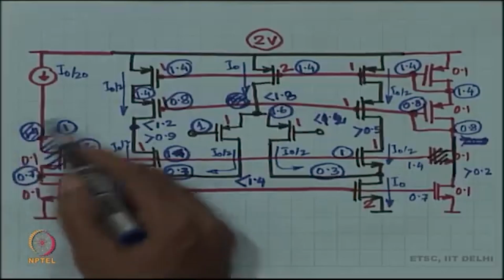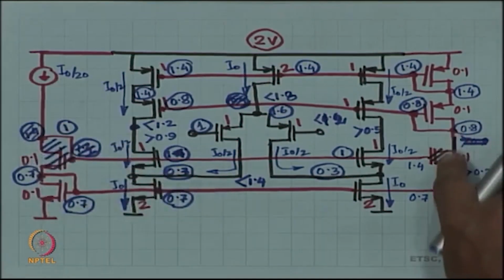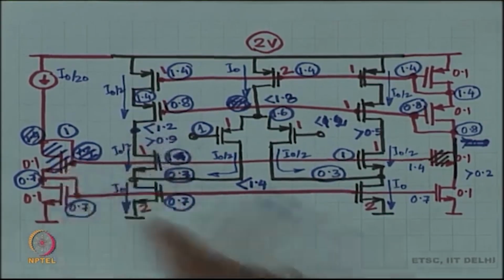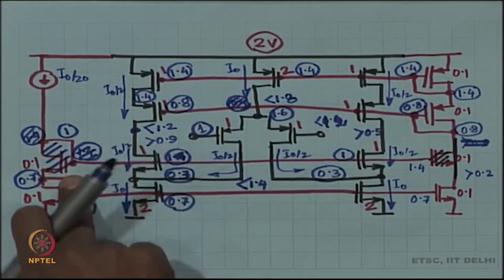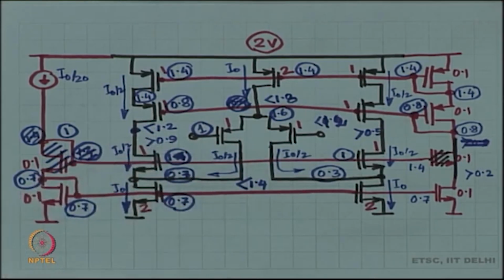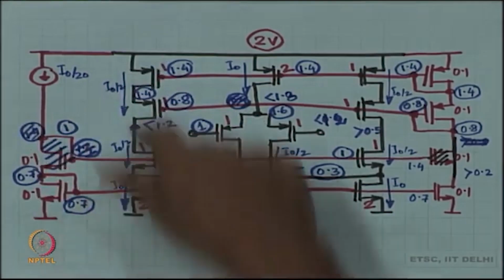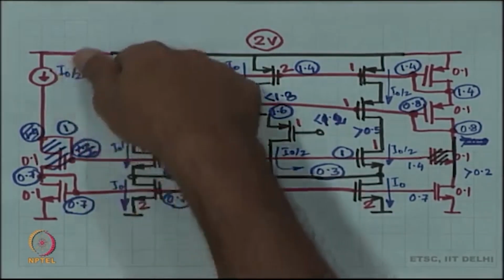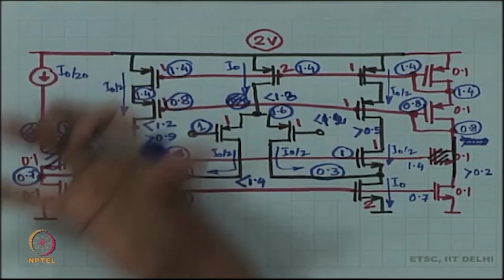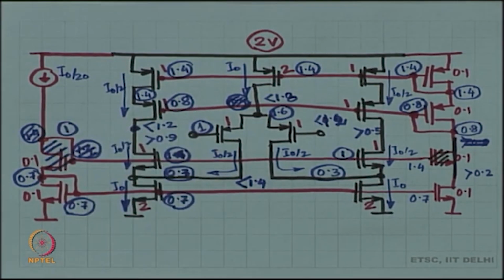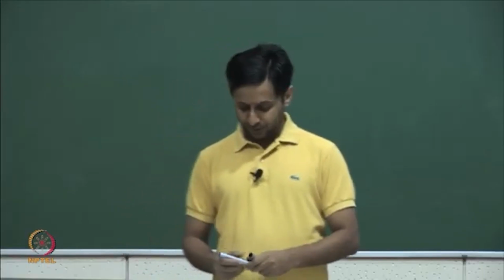You have to set this side. So, we removed this device, we removed this device as well. We need to have a lower voltage over here. How do we get a lower voltage? You can do other tricks. You can have another current source, small current source, and pull a large amount, have a large device, have a lesser VGS minus VT, all kinds of other tricks you can implement to get a lower voltage out here. It just has to be a stable voltage, that is all that is needed. All right. So, this is the folded cascode amplifier.